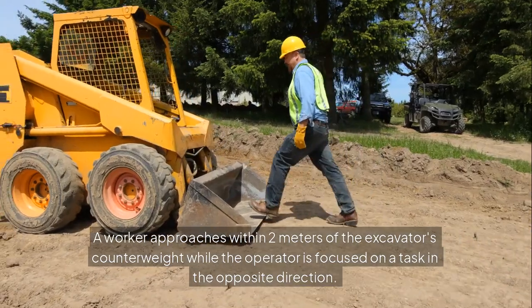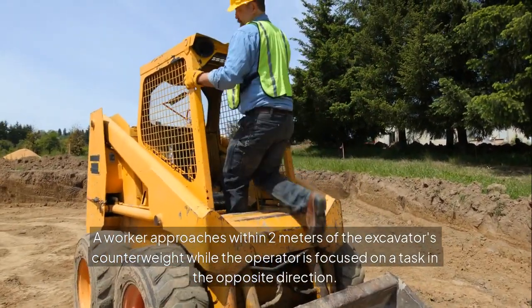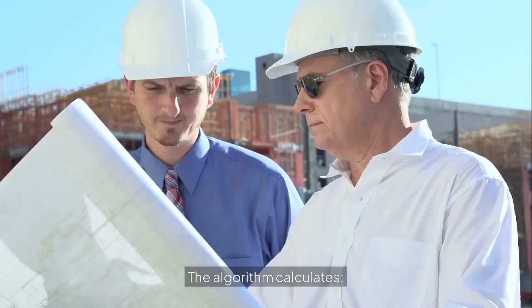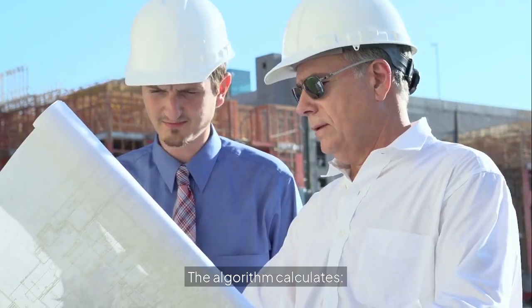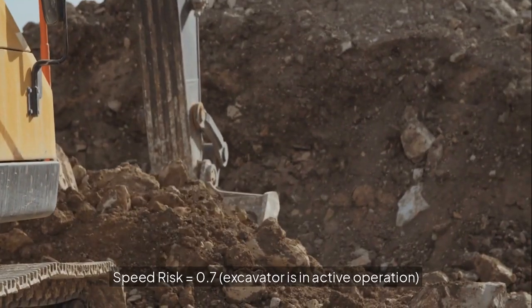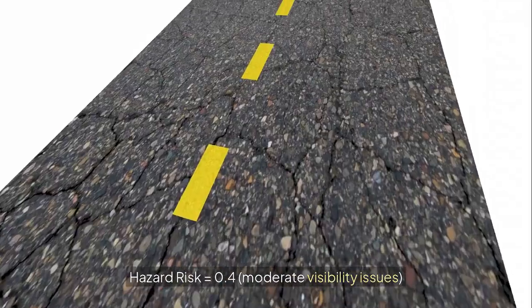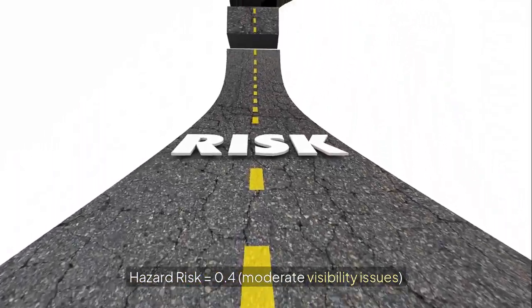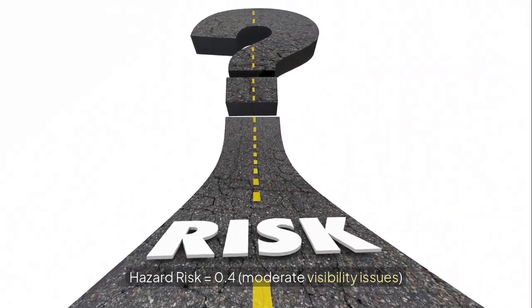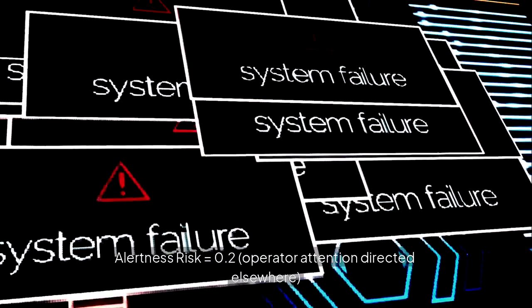A worker approaches within 2 meters of the excavator's counterweight while the operator is focused on a task in the opposite direction. The algorithm calculates proximity risk equals 1/2 equals 0.5, speed risk equals 0.7, excavator is in active operation, hazard risk equals 0.4, moderate visibility issues, alertness risk equals 0.2, operator attention directed elsewhere.